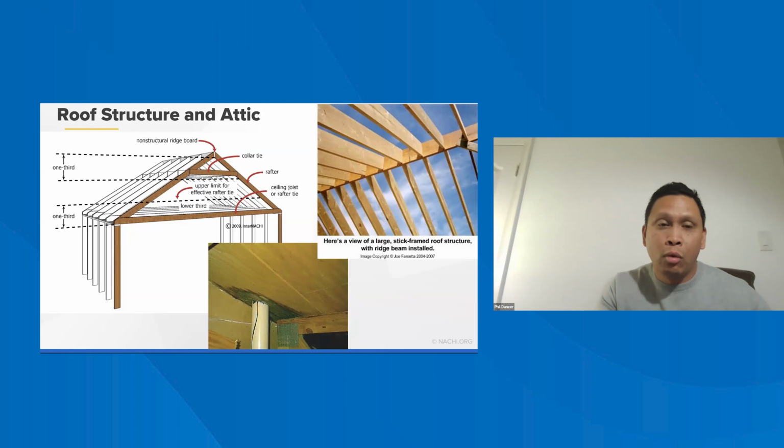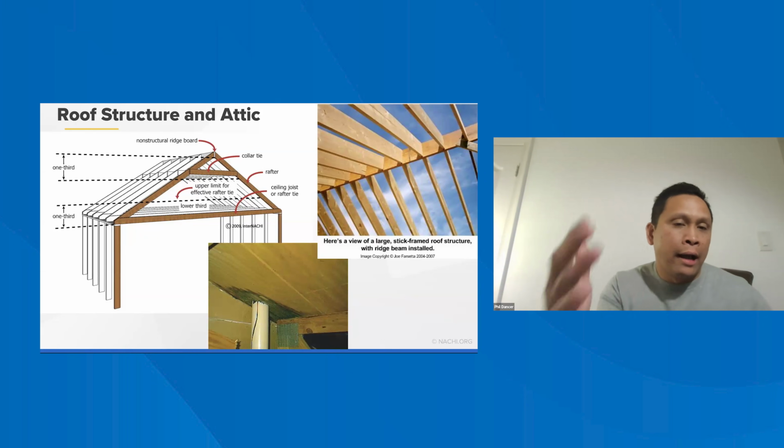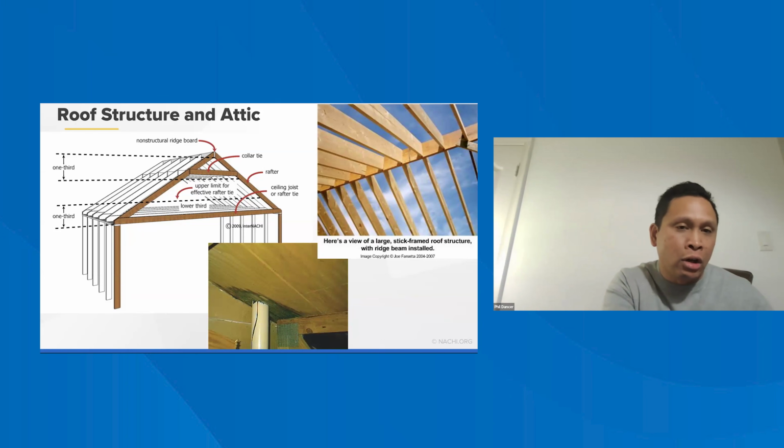But one of the things that I always say is, when in doubt, call it out. And just say, hey, I typically see a double top plate installed here. Recommend to ask a builder to check their plan details to see if they need one.